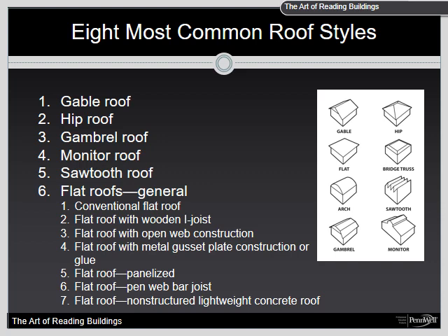The hazards are threefold. 1. The 3/8 inch stem and the 2 by 3 inch or 2 by 4 inch chords will take little time to burn, weaken, and cause rapid collapse of any roofs sufficiently undermined by fire. Unfortunately, many buildings can be found with unprotected chords. They are often painted a dark color to minimize their presence.